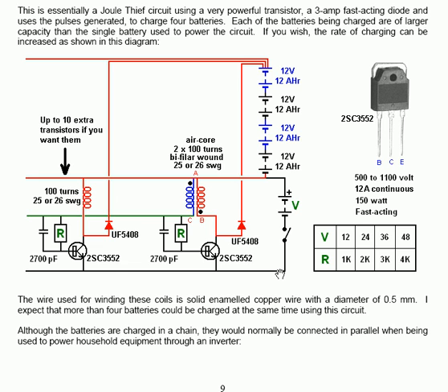Again, he has a 2700 picofarad ceramic capacitor connected across the resistor R, feeding the transistor. He does show a similar 2700 picofarad across the resistor feeding current to the second transistor, though he does say that it's not necessary to do it. You can have it or you don't have to have it, because the first one will operate satisfactorily for all of the transistors in the circuit.